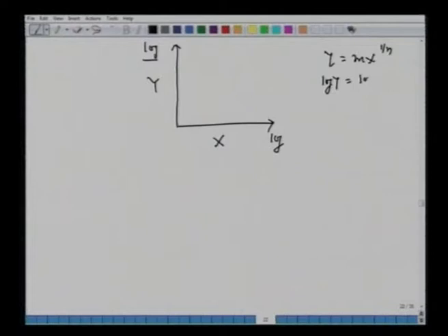In other words, on a log scale plot of y versus x, we have y equal to m x to the power 1 over n, so log y equals log m plus 1 over n log x, and from this we obtain the values of m and n. So the Freundlich isotherm is linear on a log plot. Read from the graph at Y1 equal to 3.3, this should be equal to 565, or you can solve from the equations.